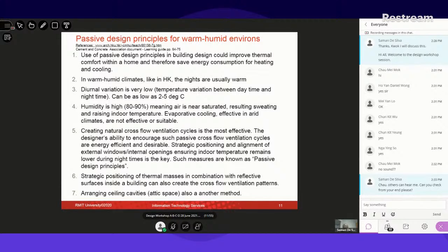Okay, so that is what is happening. So relative humidity is one of the major issues. It is very low here, very high in your part of the world. So that is when you wanted to have that situation, cooling systems are slightly different what you are using. For an example, evaporative cooling systems are effective in arid climates where I just explained as Melbourne, but it is not very effective in Brisbane or Sydney, or to that matter, Hong Kong. But you have to find a different systems.